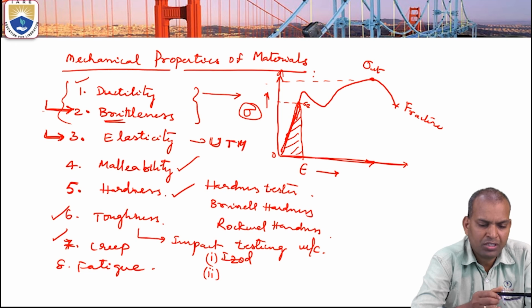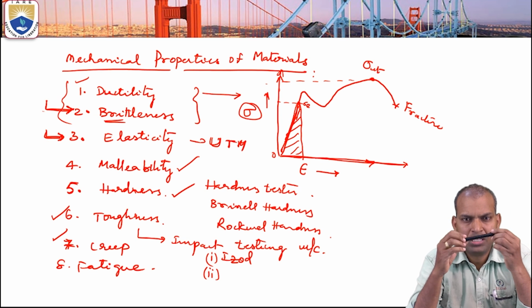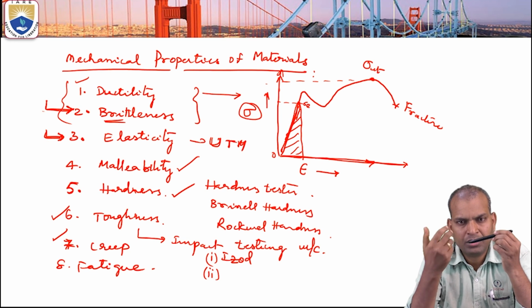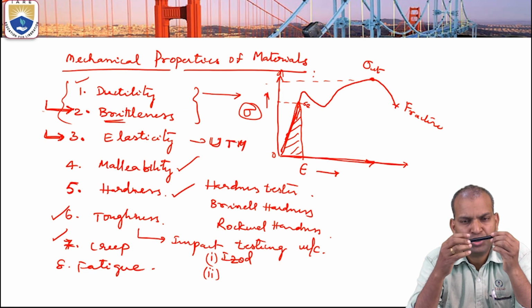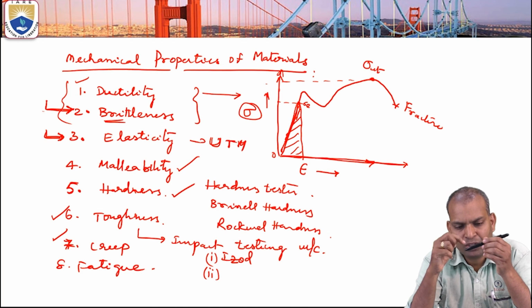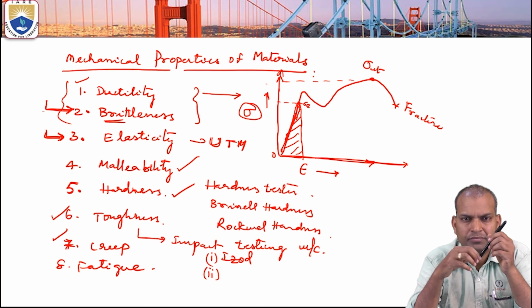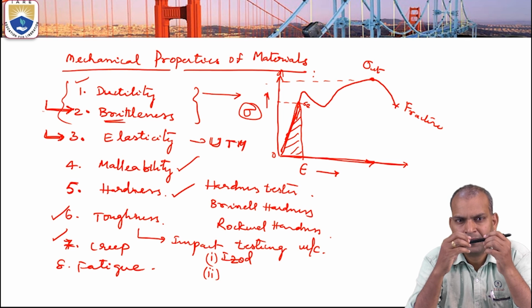The chuck is a component of a lathe machine. When the chuck is under rotation, the shaft is subjected to cyclic load. So the shaft should have fatigue strength. If the shaft has a ductile nature, when a load is applied, it will bend. Bending stresses lead to deformation.